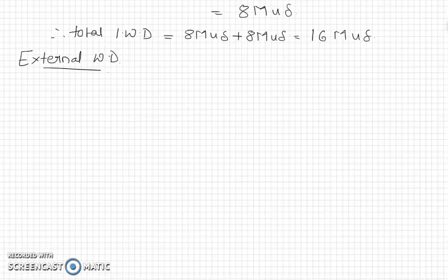Again, this will have 2 parts, external work done for the positive and negative. But what happens is, when we say external work done, the total load, that is W, acts on the entire slab together. So when it comes to external, it doesn't get divided into negative and positive separately. It's a whole one quantity of load that is acting on the slab. So it will be only WU. Okay. So load, but we have 4 segments with us.